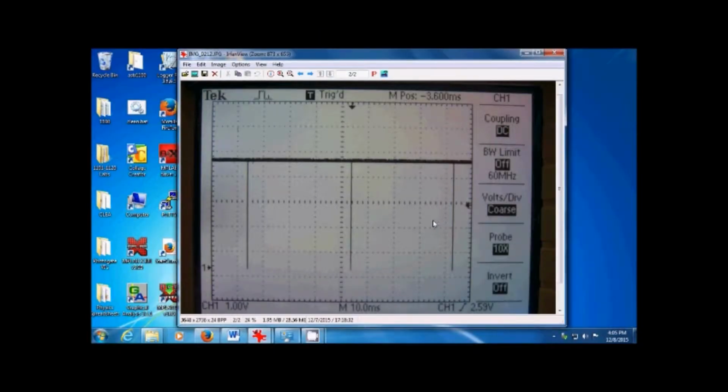Now say that you have sped up your code 1,000 times like you're supposed to, and you've set your LEDs blinking at the slow or the moderate setting, and you're now looking at it on your oscilloscope screen, but instead of seeing well-defined square waves like you're expecting, you see something like this, where you've just got these tiny little spikes. What's going on? Well, there's something in your code that is screwing up your timing. I know exactly what's causing that, but I want you to figure it out.